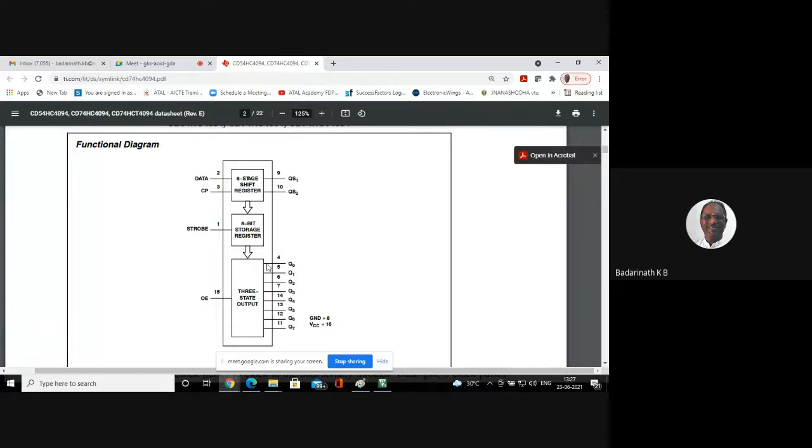So if you are using this pin, you put either 1 or 0. When you're not using these pins, which may be connected to other buses, other signals and so many things, you have to disconnect them from the circuit. What do you mean by disconnect? You produce high impedance. High impedance is nothing but a disconnect. So that is called the 3rd state, or high impedance output.